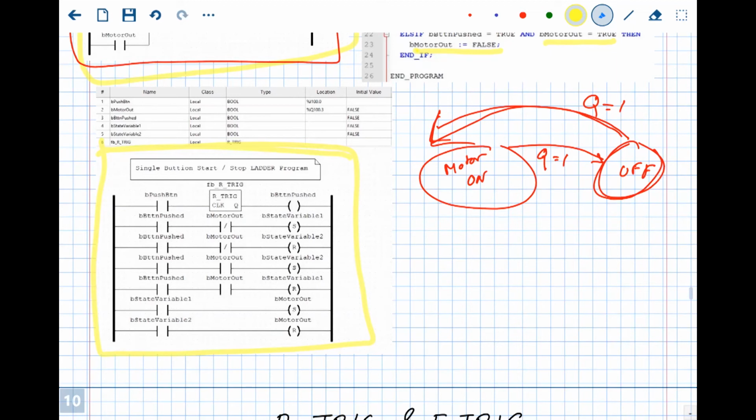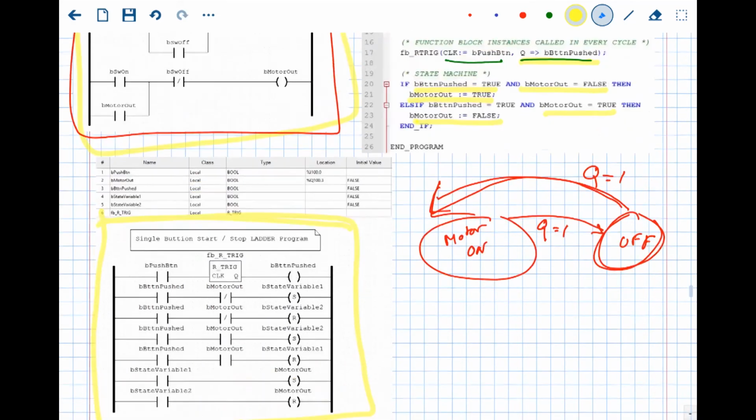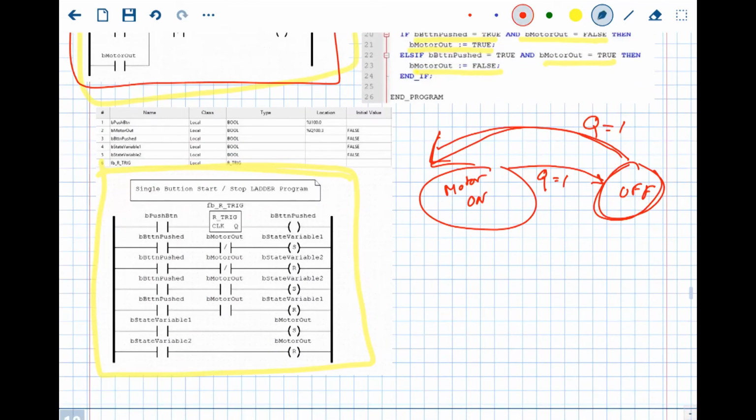And I think, Nathan, as you were asking, how does the state machine work? So this state machine over here is implemented in a ladder-based system in this part. So if you see these 4 cases, there are 2 state variables which are being set and reset. This is being used to formulate the state machine in ladder.